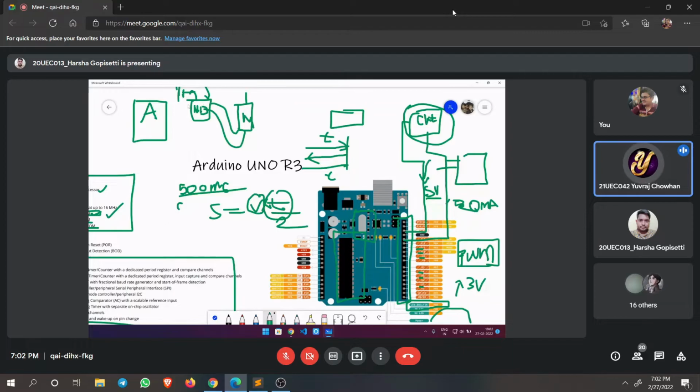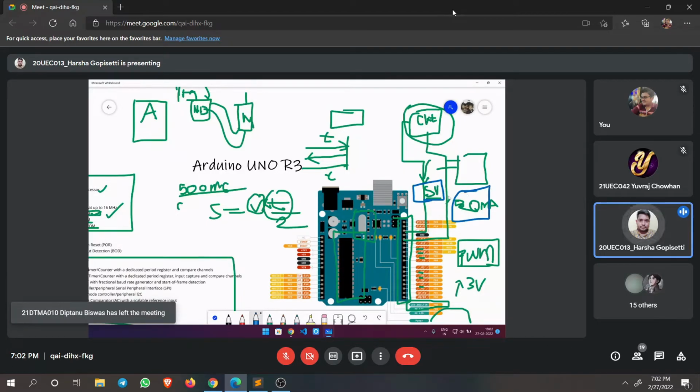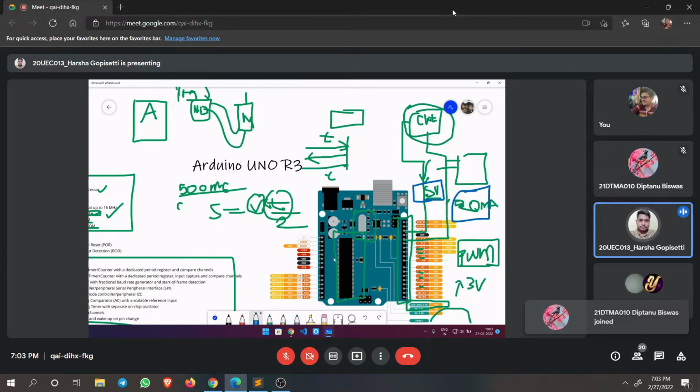So, what is a motor drive? It is a module. You are having 5 volt and 20 milliampere. It is very little power to run a motor. It will cause this Arduino to burn. If you try it in TinkerCAD, it will work. But in practice, either your microcontroller will burn or the motor won't run. To achieve that, we will be using a motor drive.